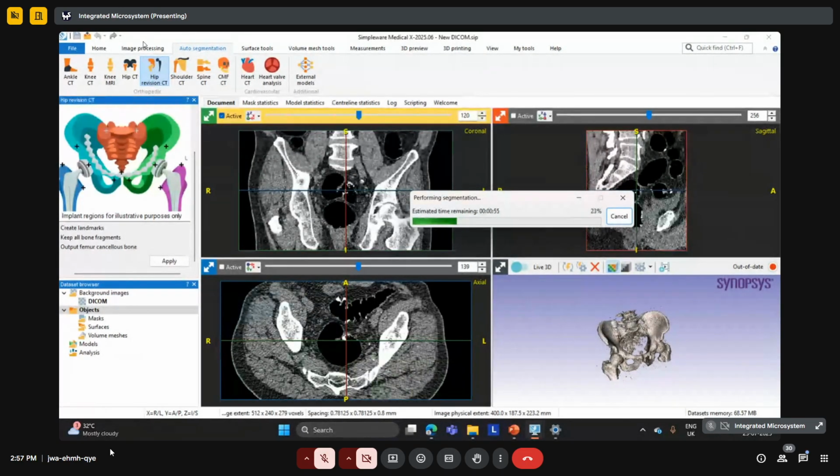Also, yesterday we have shown that there are various presets that we can directly select to segment out anatomy. We have a preset value set for bones from 230 to 3070 or 3000, and then we have for muscle 0 to 140. For skin we have minus 729 to minus 129, and then we have for the air region that is present to segment out the lung region.